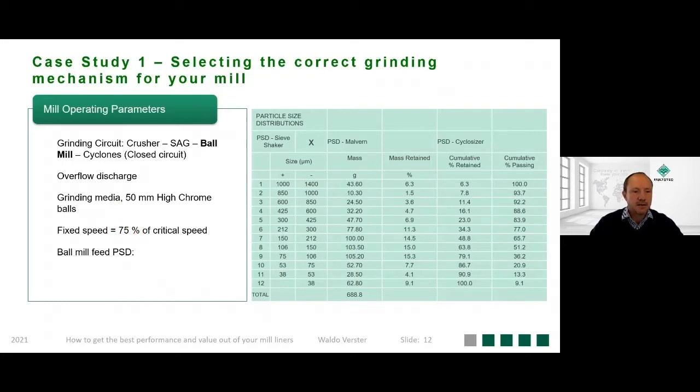And then the feed size of this ball mill. Extremely small feed size, top size here of 1.4 millimeters. And we will see later on why this is so important. So remember, fine feed size plus an overflow discharge.